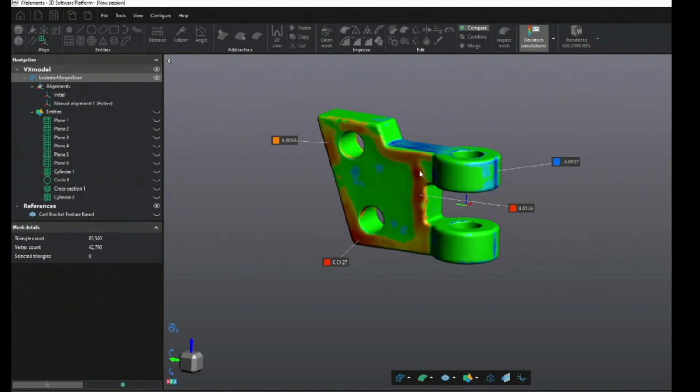But we put a best fit plane across that. You can see we're slightly shy in some parts in the center and slightly proud in some parts of the edges. If the customer said, I want the part to represent the maximum outer boundary of this side of the part, we could apply a max fit to that plane instead, as if you had taken a plane and just set it down on the side of the part, touching off on the furthest point.